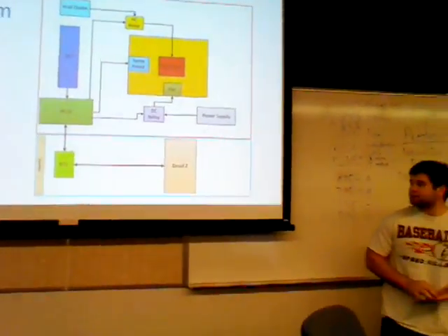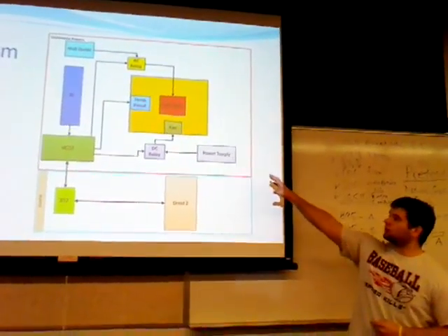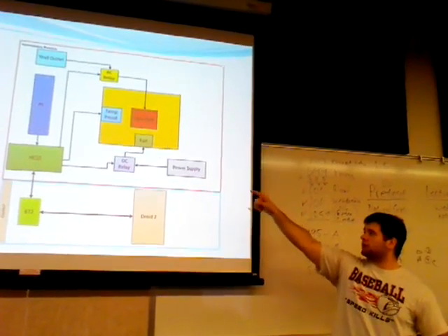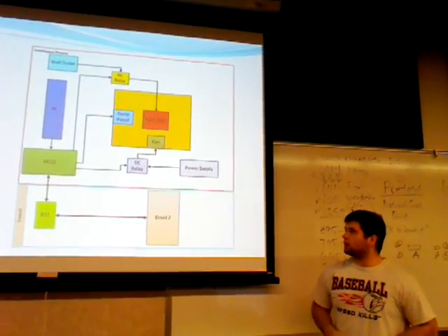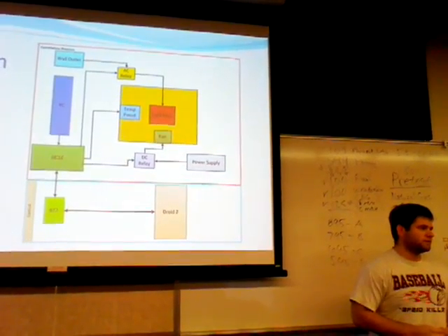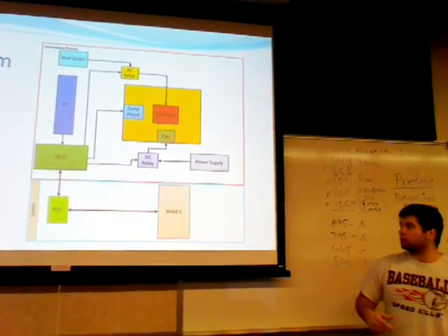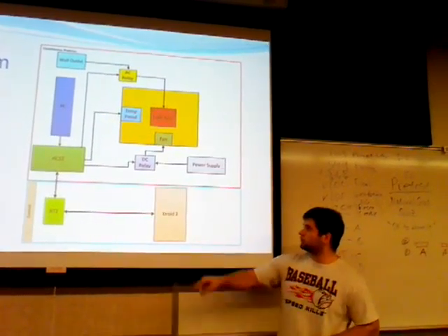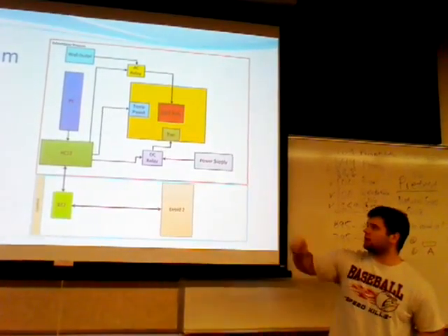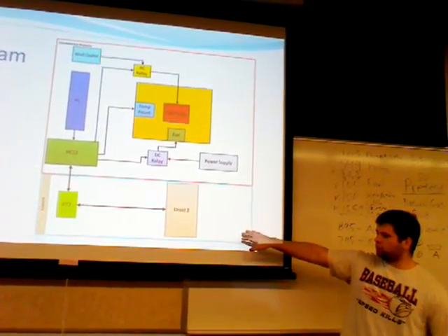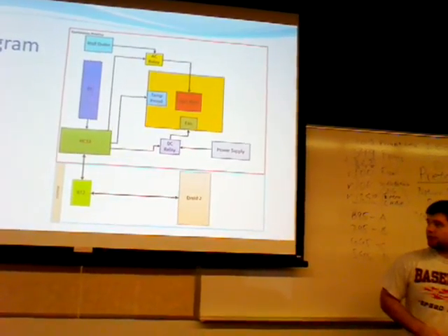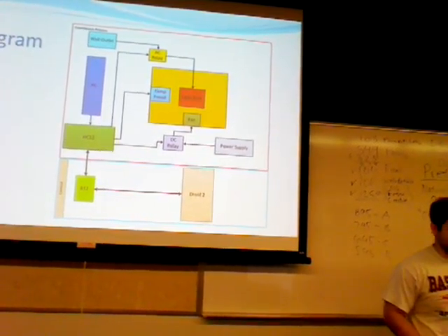And here's a block diagram, and the top part is the continuous process. You're going to have the temp PMOD reading the temperature in there with the light bulb and fan, and based on the temperature that the PMOD reads back, I will have thresholds, a high and low. If it gets above or below that point, it will turn on the outputs, which are connected to the DC relays, or DC and AC relays, and it will then turn on either the fan or the light. And this is the control portion, which has my phone, and it will talk to the Bluetooth, which will then set the thresholds and the desired temperature.